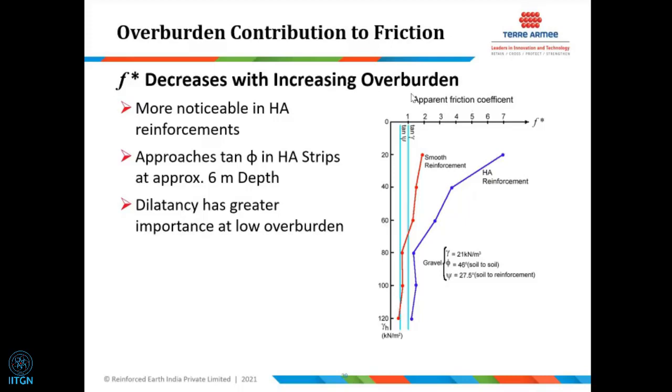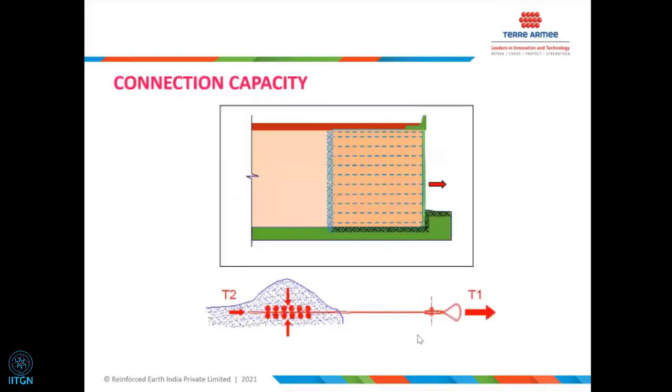This clearly defines that the coefficient of friction in the top layers is much higher than the normal tan phi value, and that's how this distribution is considered. When doing the pull-out checks, you multiply that coefficient for the respective reinforcement layer, and you calculate the resistance.